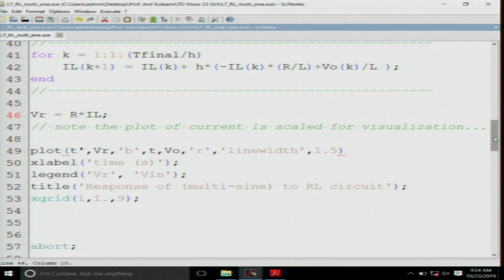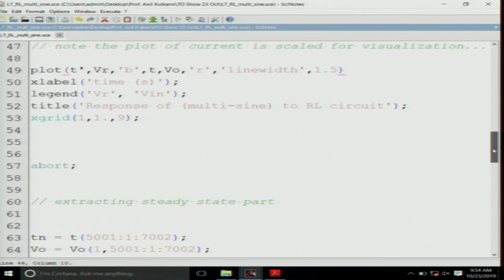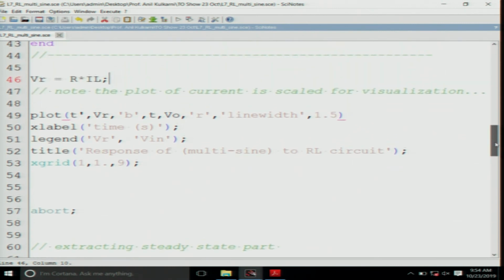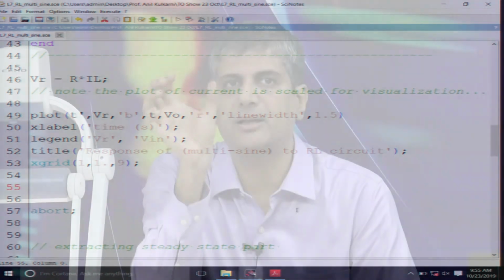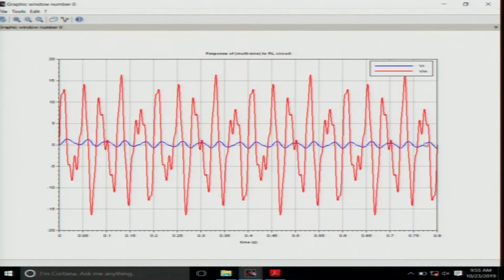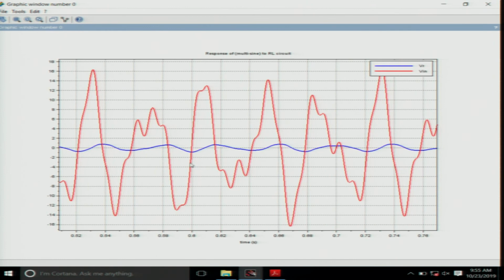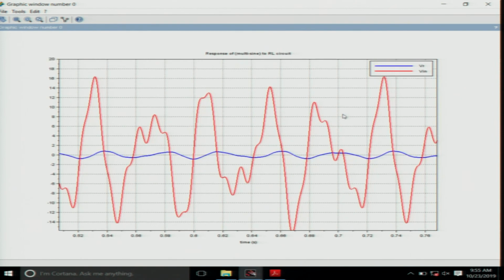Yeah, if you want to take out the Fourier series of a signal, what you need to do is isolate one period of the sinusoidal steady state. So, what you need to do is take a window of 5 hertz. He is showing it using the arrow. So, this portion, okay. You take one fundamental period. In this case, since it is 25 hertz, 40 hertz and 100 hertz, the fundamental frequency is in fact 5 hertz, okay, of this composite signal.